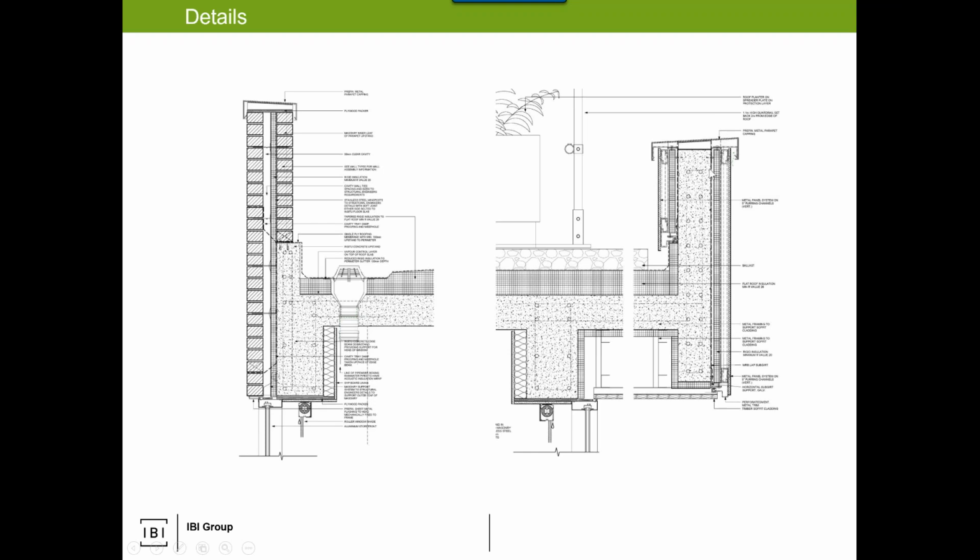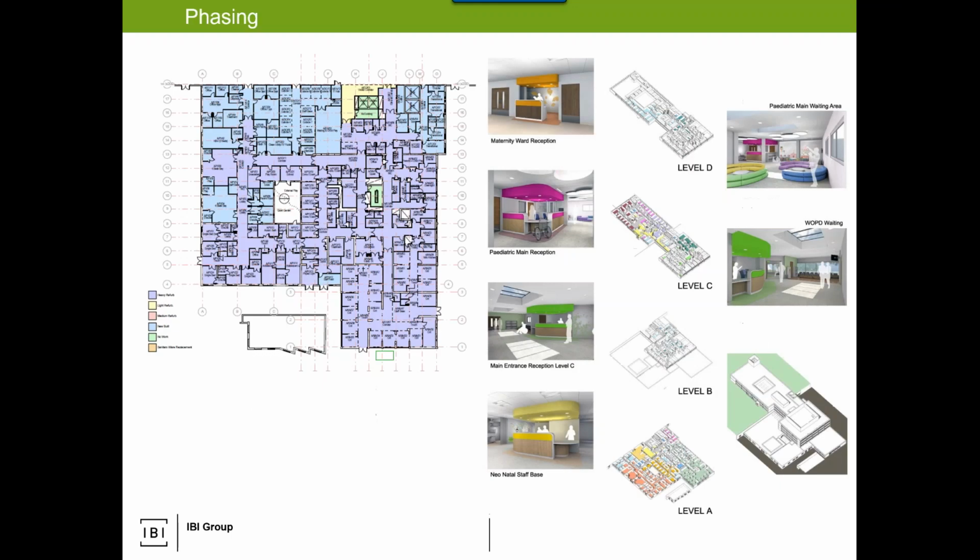So oftentimes the model has the concrete slab and walls, and maybe a generic representation of the flat roof, then the handrail, and maybe a generic finish, so one component for this finish, and a component for the parapet. You bring those into the detailing world, and then you'll have a 2D overlay in Revit, or EcoSim, or whatever the tool is, to actually represent the finer details at the more 1:5, 1:10 scale. There has to be the proper balance between what we're modeling for BIM purposes and what we're modeling for contract documentation.